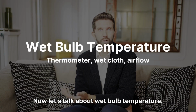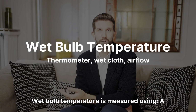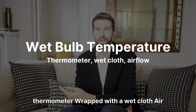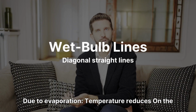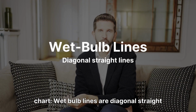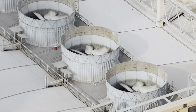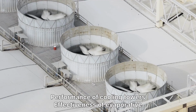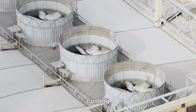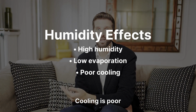Now let's talk about wet bulb temperature. Wet bulb temperature is measured using a thermometer wrapped with a wet cloth, with air flowing over it. Due to evaporation, the temperature reduces. On the chart, wet bulb lines are diagonal straight lines. Why is wet bulb temperature important? Because it tells the cooling potential of air, the performance of cooling towers, and the effectiveness of evaporative cooling. If humidity is high, evaporation is low, and cooling is poor.